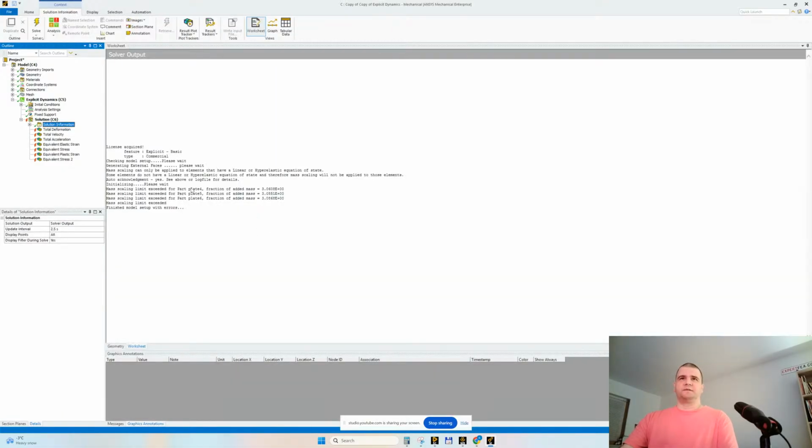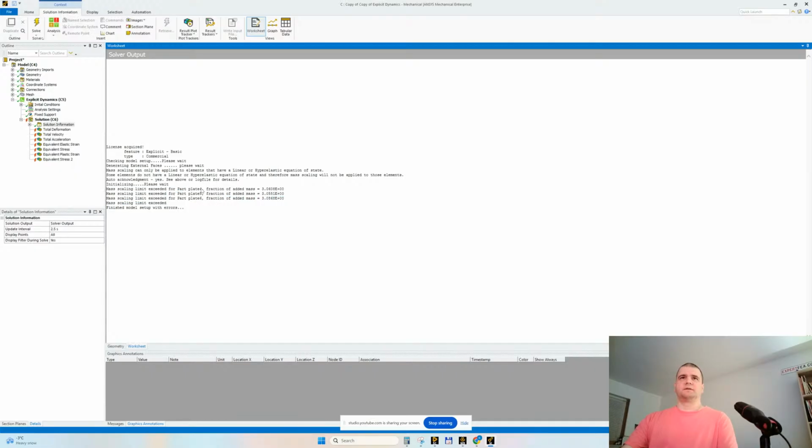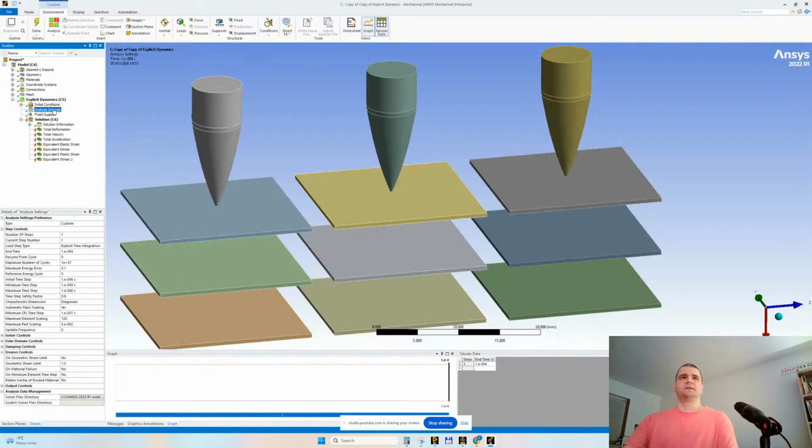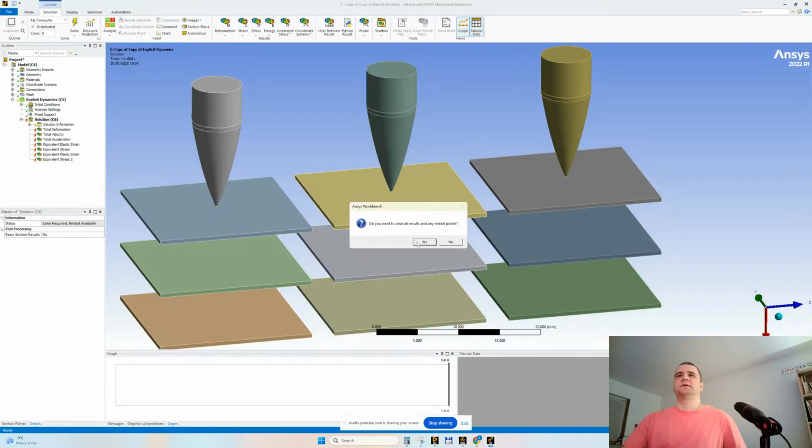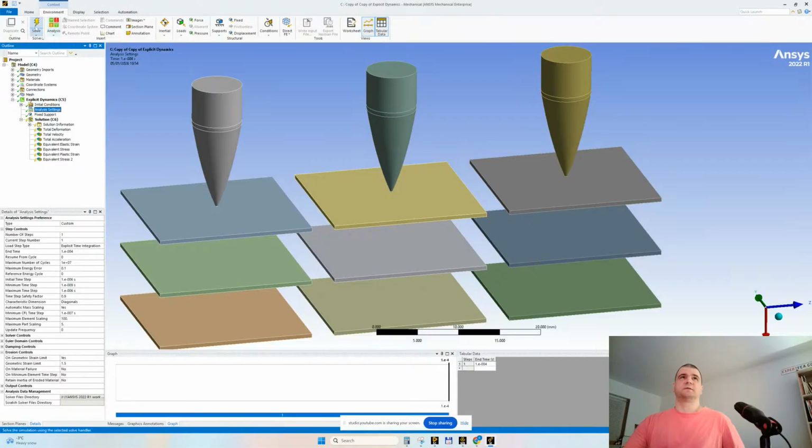The one easy solution for this is to go here and change this part scaling. Instead of 0.05, maybe to 5, 10, 50, big numbers. Right click, clear generated data. This mass scaling is very useful. It's very much time saving. You'll see in a few seconds.